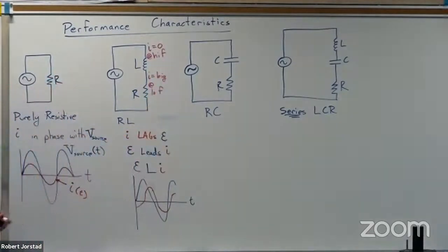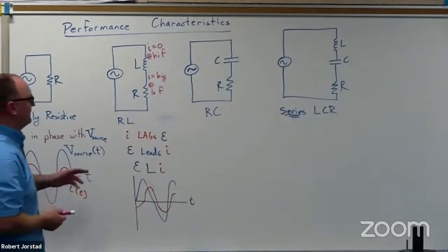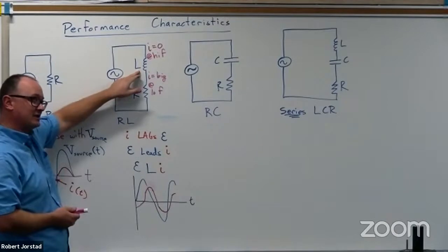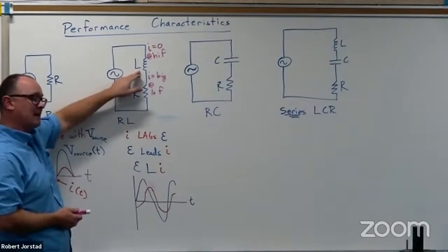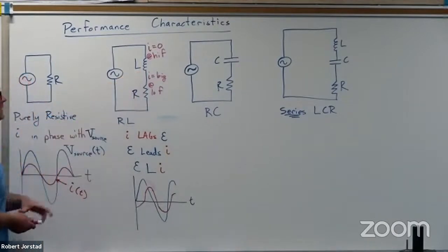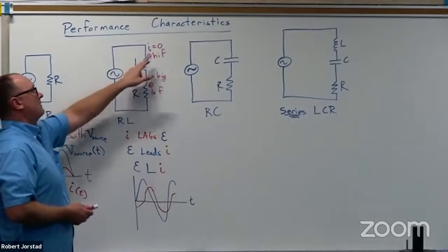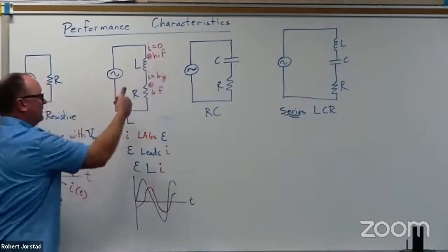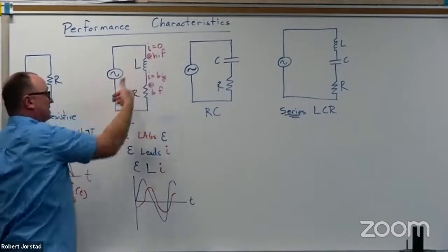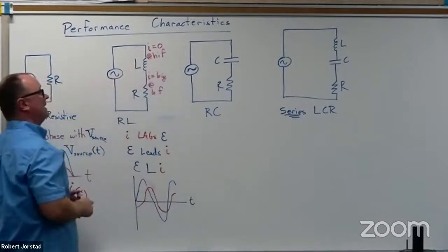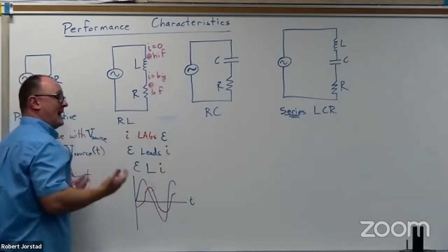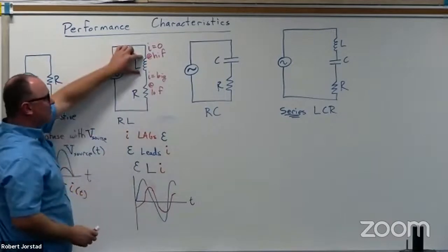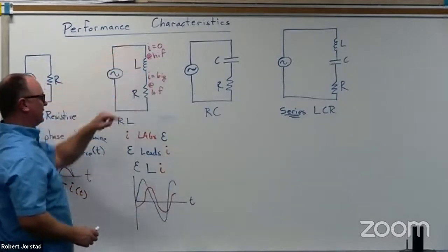Now let's think about this quickly. What does an inductor do? It's a coil of wire. It opposes changes in magnetic flux. If you have the current changing rapidly, that solenoid is trying to change so rapidly that it has a huge back EMF, or it opposes the change so much that it basically has a huge voltage across it and clamps down on the current.